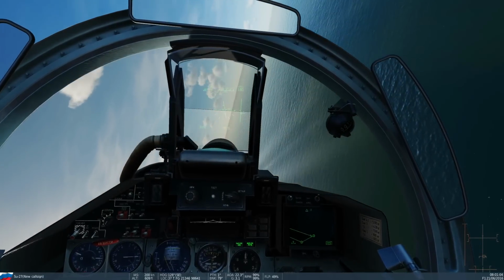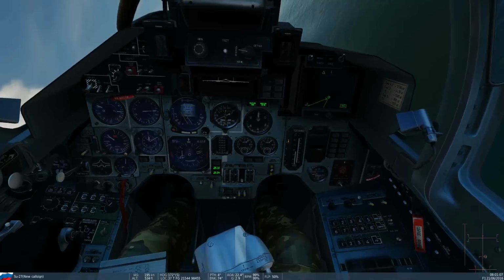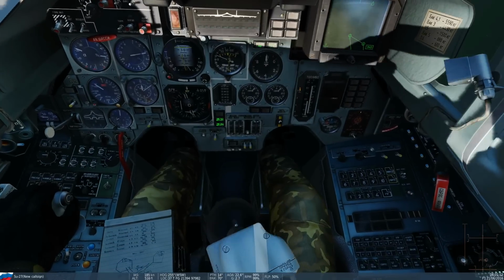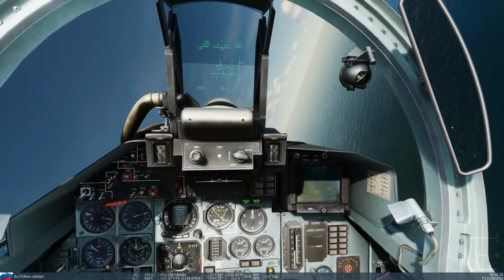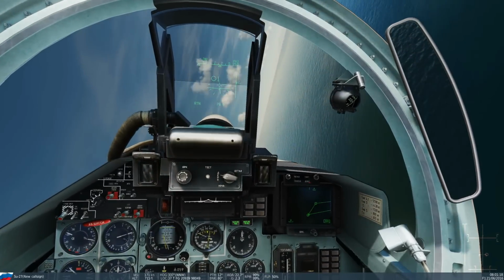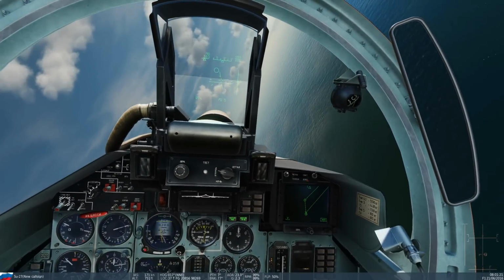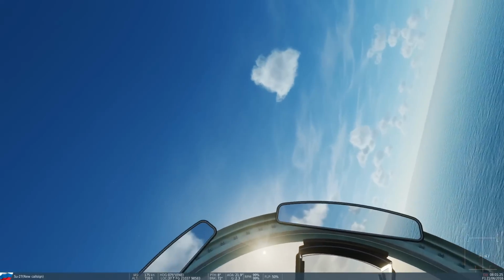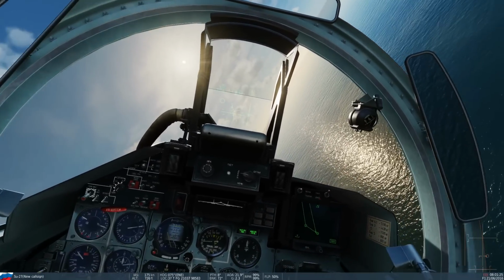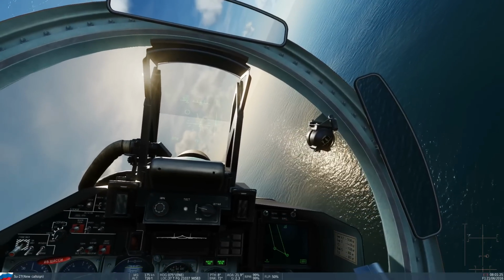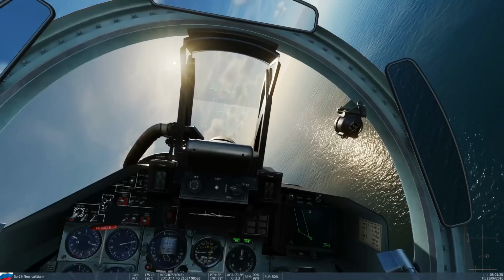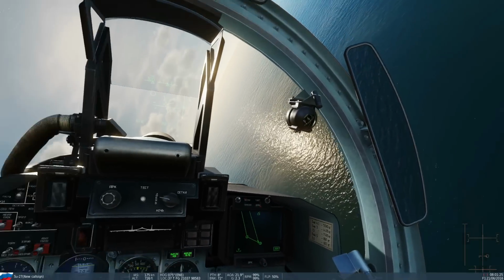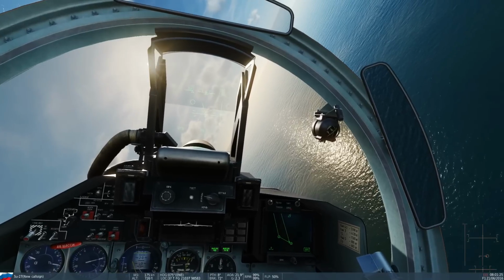Now, I'm probably just going to fall out of the air at this point. I definitely did it. Just maintaining just the same. Try Y again. Yeah, it's the same. Whether Y is on or not, it's going to sustain the same. Shouldn't be any different, because whatever I'm commanding is more than the plane can fly at. I'm commanding all of the alpha. The plane can only fly, due to the shape of its wings, its weight, shape of the body, thrust, and so on, at a certain sustainable angle, and the augmentation system will tell me what that is. Let me try with augmentation off, just out of interest.